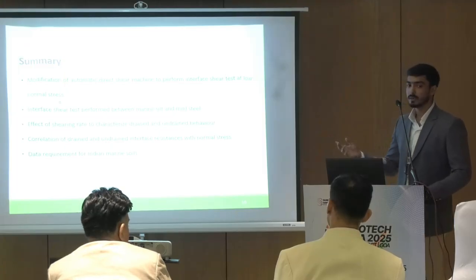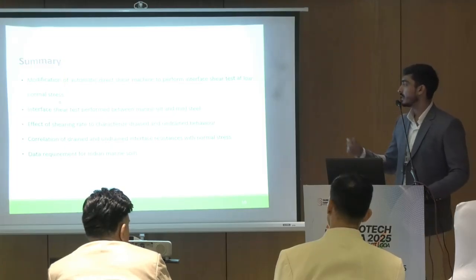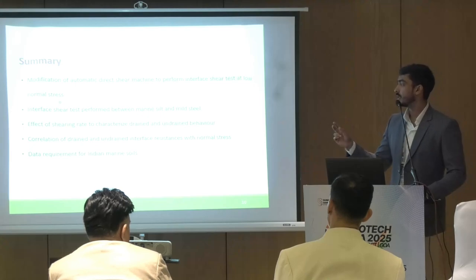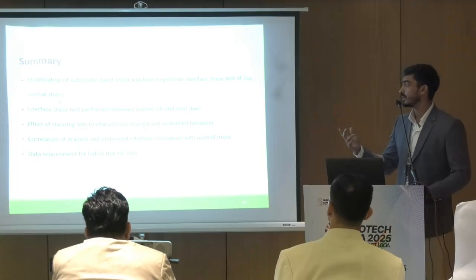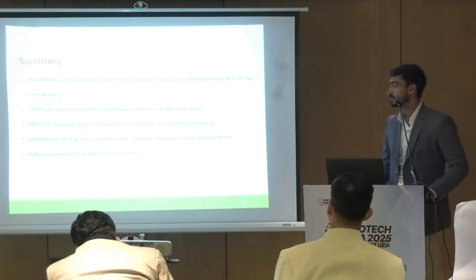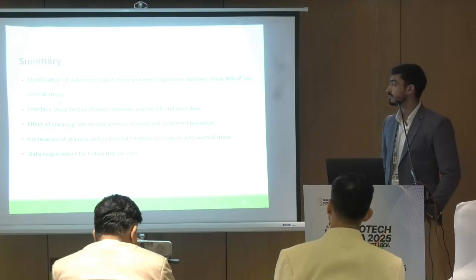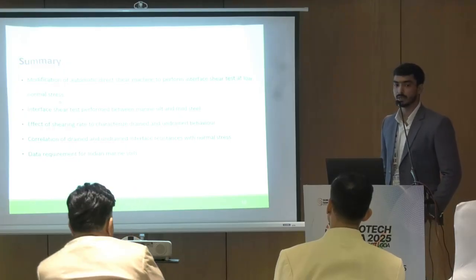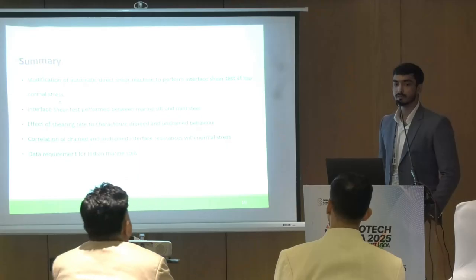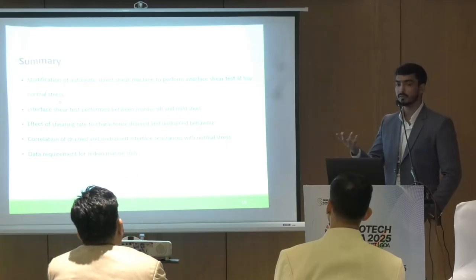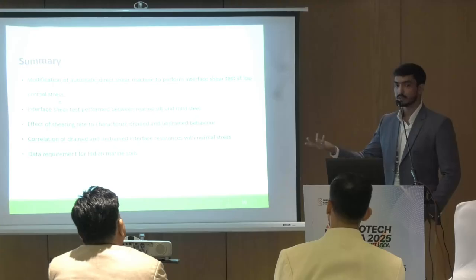We correlated our drained results, and from the undrained equation we back calculated the excess pore water pressure which may come. And as we are talking about offshore, for Indian environment we need more soil data, so that in future if any kind of project will come, we'll have the soil results.